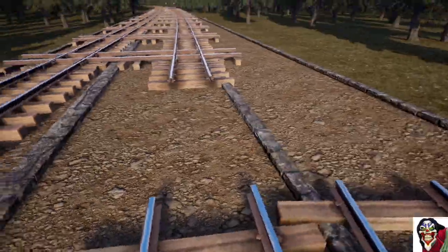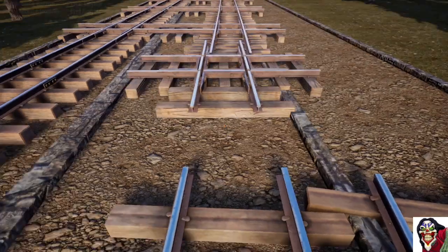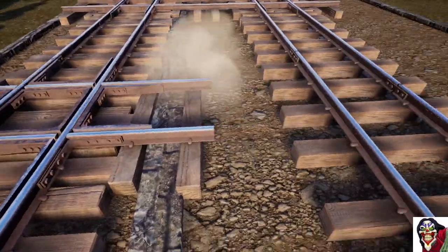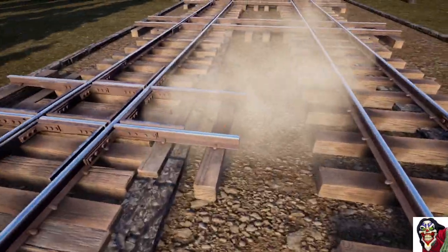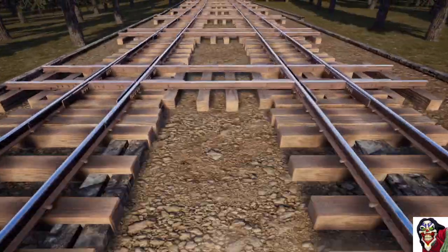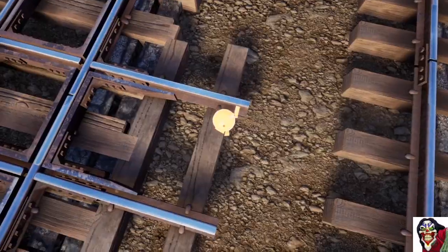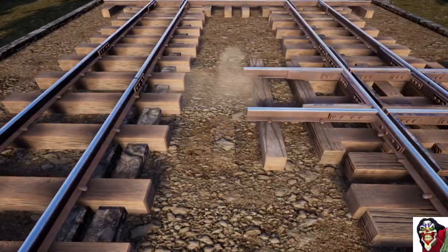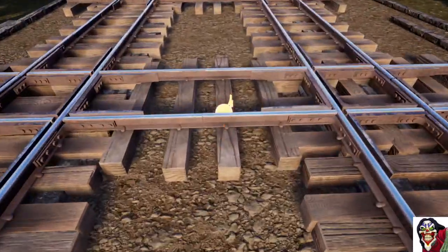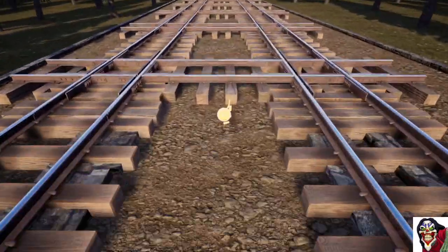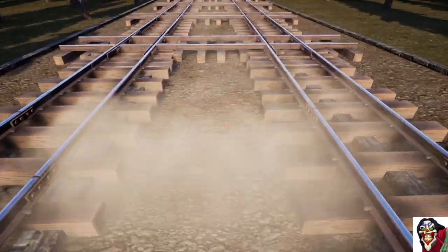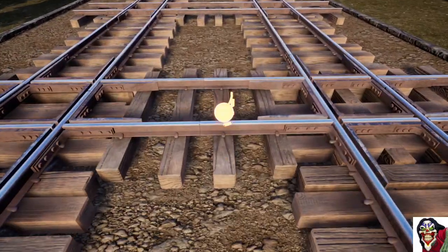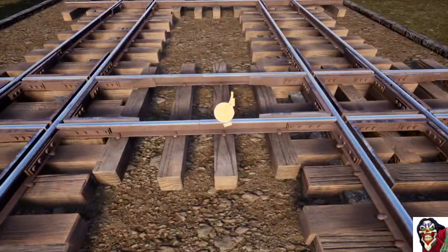Oh, we don't want to delete that one. We're going to put it back because we need that one for building the curve. Delete all these ones in the middle. Yes, if you do the outside lane, when you do the inside lane, the length is actually slightly shorter. And if you do the inside lane first and move it to the outside, it will make that tie spacing very slightly longer than the 7 tie spacing, and you'll end up with gaps in your ties.